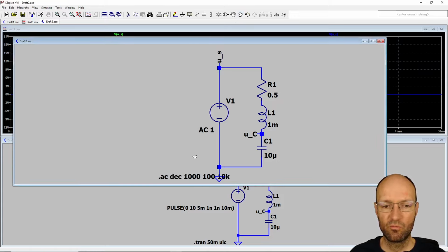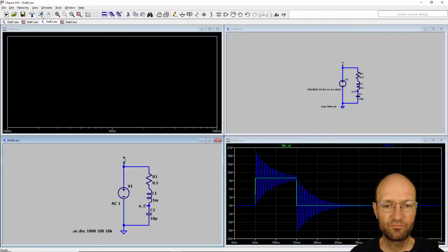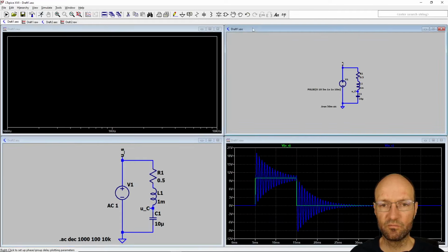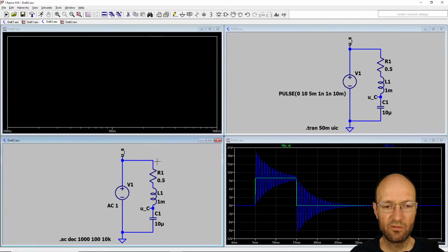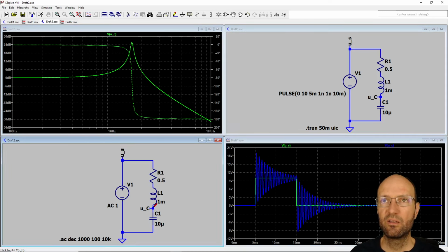And okay, so then with this circuit we can also start the simulation here and get a second plot. And if I also take a look at the output voltage here, then we can nicely see, okay, it's starting here, so it's a dB scale, so it's starting with 1 because at low frequencies the capacitor is acting like an open circuit, and so there will be no current, and all the voltage of the source will be visible as a voltage drop across this capacitance.